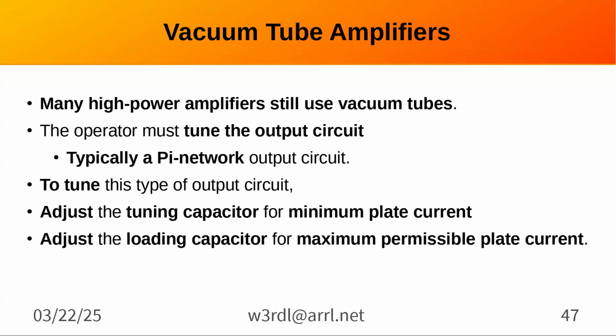But you do have to go through the tuning capacitor and loading capacitor bit, which I guess, plus the heater, you get this nice orange glow. And usually the output is a pi network. So you're adjusting the input and output capacitors in the pi network as the load and plate adjustments.